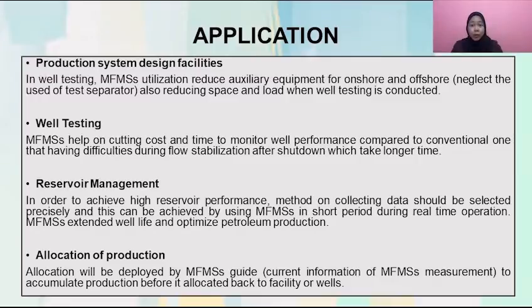Okay, for the third point is reservoir management. MFM can provide real-time continuous data to enable operators to characterize field and reservoir performance better and react faster. For example, changes in gas or oil ratio or water cut can be detected and quantified immediately, whereas traditional test separator provide information about only cumulative volume at discrete point in time.